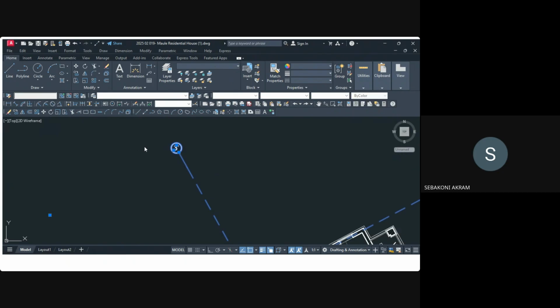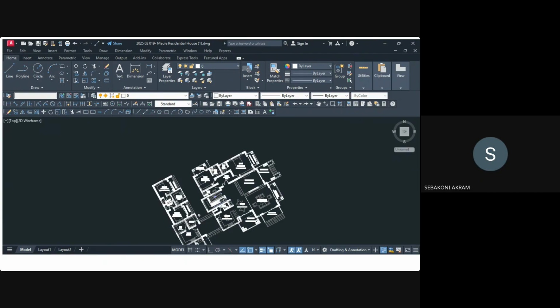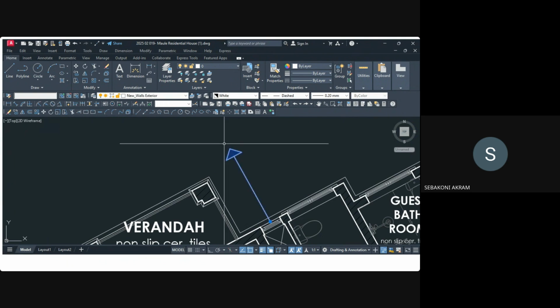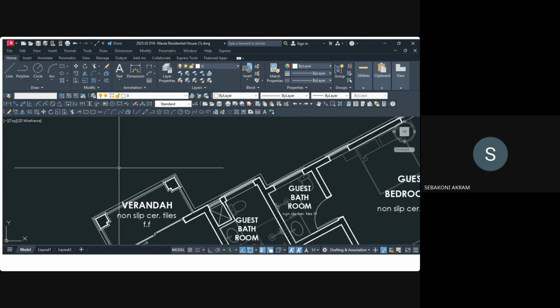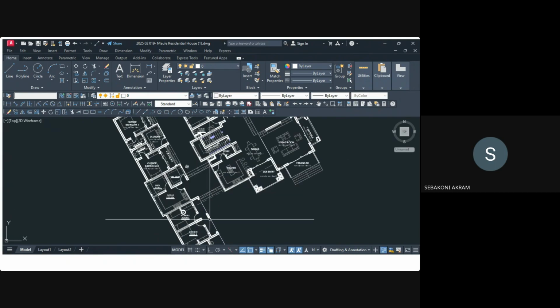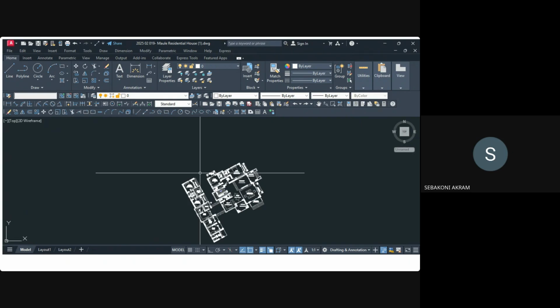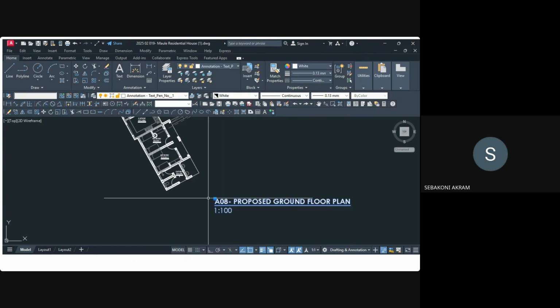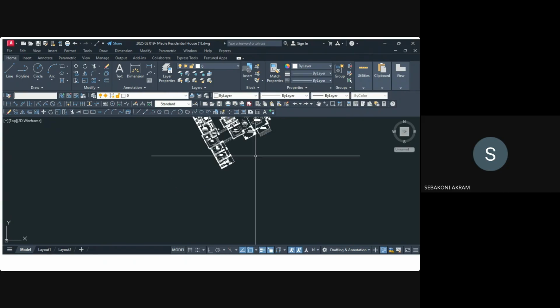For the meantime, I'm going to show you how we clean them later. Let us first isolate them off so that we clean the drawing first. So you come to isolate, you hide the objects. Have you seen? It is not deleted, but just hidden. I'm seeing that direction was for the manhole, so we can delete also that arrow. So we are remaining with this. We already know that this is the floor plan, so you can also delete that.